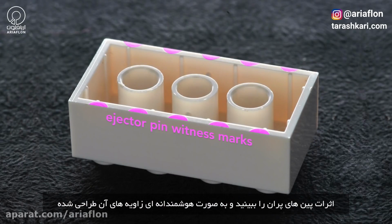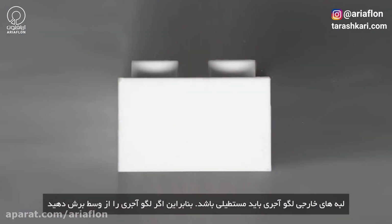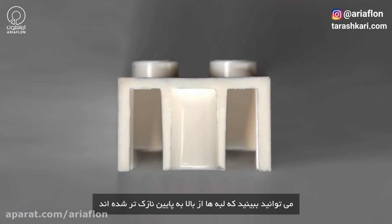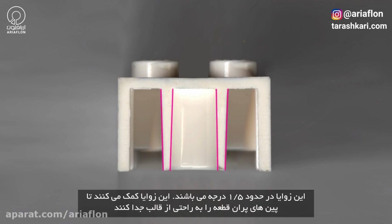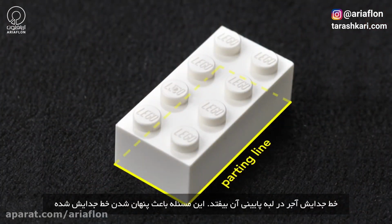And what's most clever to me is where Lego designs their draft angle. The outside of a Lego brick must be square. So if you cut a Lego brick in half, you can see that these inner supports are thicker at the top than at the bottom. There's a draft angle of about 1.5 degrees. This helps the ejector pins push the brick off the mold. The core half and the cavity half of Lego molds are designed so that the parting line is at the bottom edge of the brick. This hides the parting line.